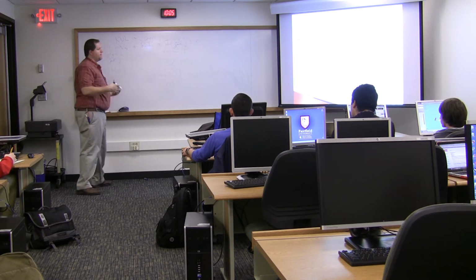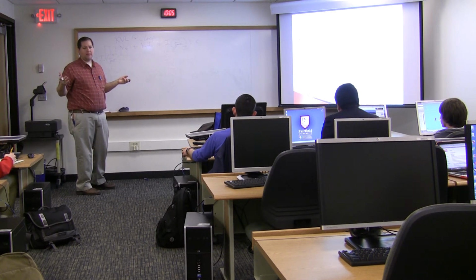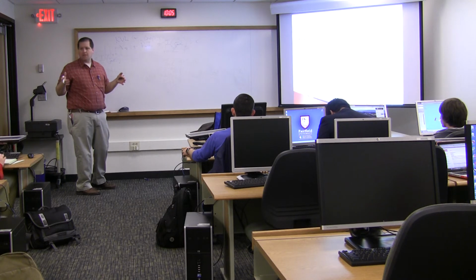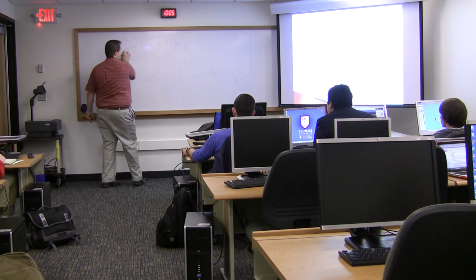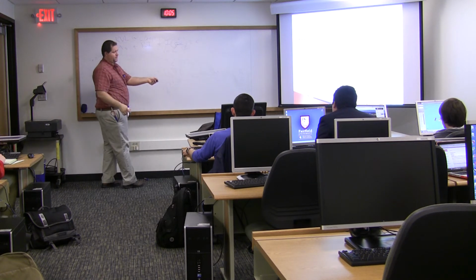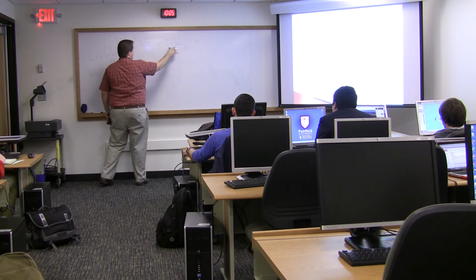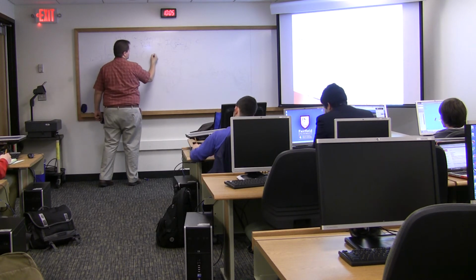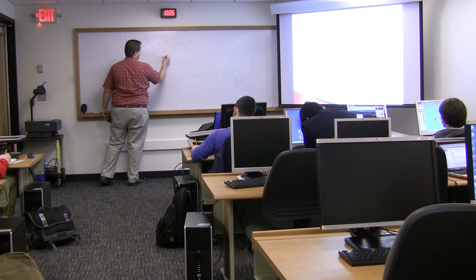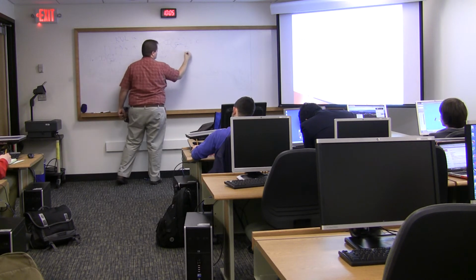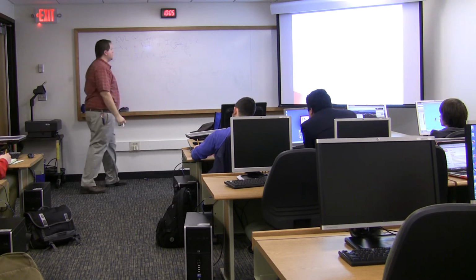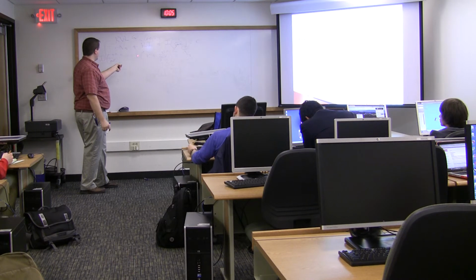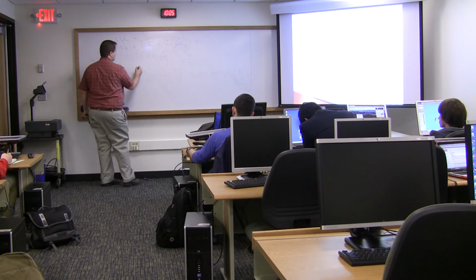So I can solve this. Vs is like a constant, basically, right? It's a variable. We don't know what it is yet, but it's not the variable we're trying to solve for. So we can treat it as if it's a constant, just as if we had defined it with a value. All right, so I can move it to the right-hand side. Let me collect my terms. So I'm going to have I times R plus 1 over j omega C equals Vs. And so now I can find I by dividing this over.